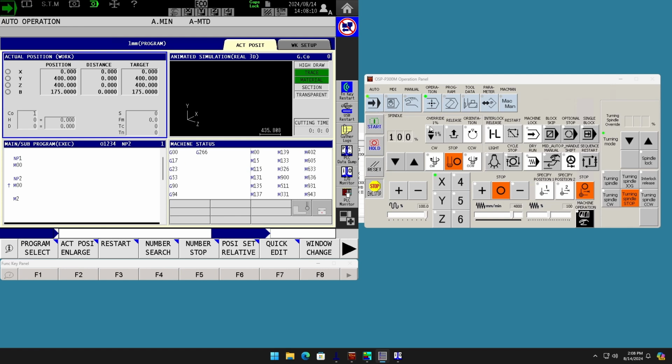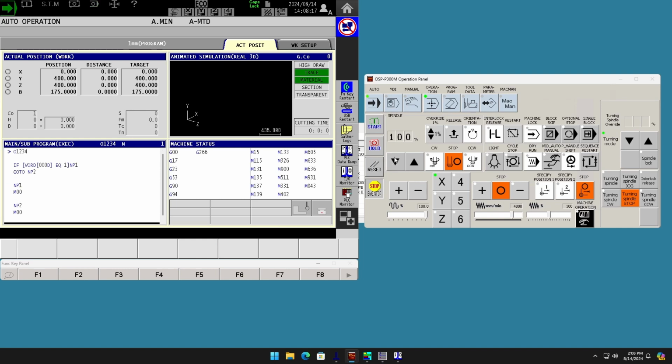What that value is actually, this button, the interlock release button, not just the button, but the actual light. So if an operator comes in and holds down the interlock release button and presses cycle start, all of a sudden they just branch to a totally different part of the program. So I've used this for things like tool life management.